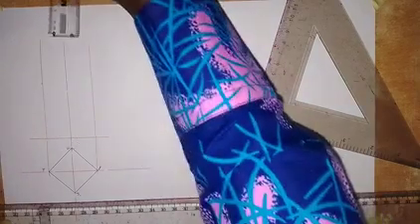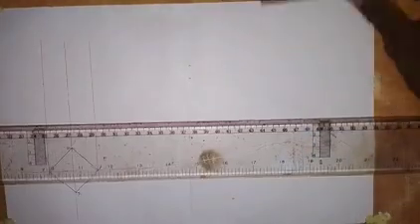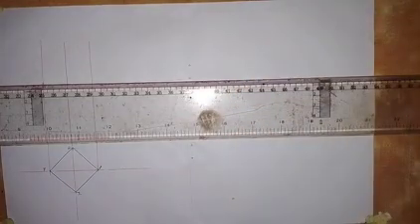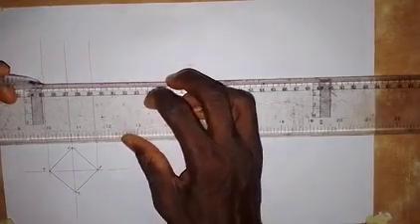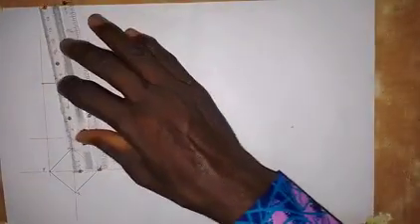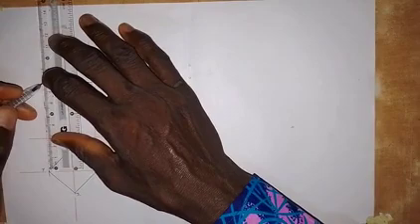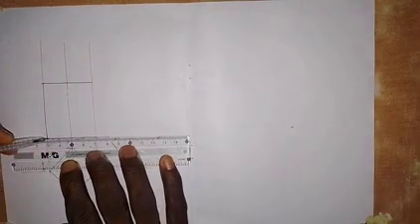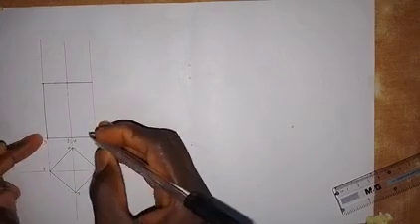So I will take a measurement of 50 millimeters from this point on the vertical line. So having taken the height of the prism as 50, I'm going to draw this line as a thick line. I'm also going to make this line a thick line. Then this base also will be a thick line. So I will leave the remaining 2 lines and I will come back to that later. Alright, so if you number this, this is point 1, this is point 2, 4, and this is point 3. So let's take note of that as we have it here.